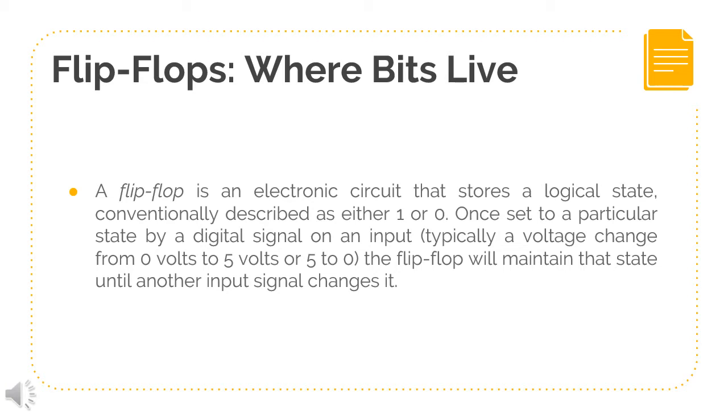A flip-flop is an electronic circuit that stores a logical state, conventionally described as either 1 or 0. Once set to a particular state by a digital signal on an input, typically a voltage change from 0 volts to 5 volts or 5 to 0, the flip-flop will maintain that state until another input signal changes it. The D-type flip-flop is the ideal storage element for saving a state inside a computer.